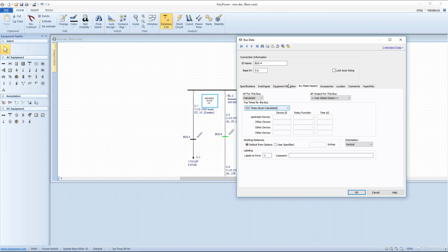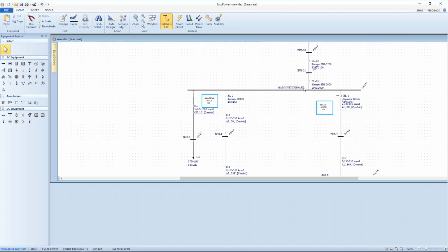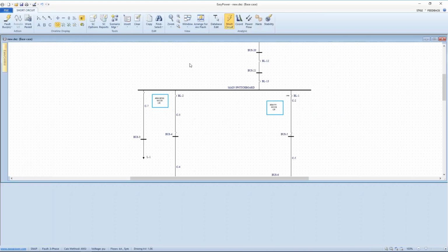we're saying we're going to auto-calculate here. We have a problem in that it will be susceptible to fault current from the main switchboard and also fault current from the battery side of things. If we go into short circuit focus, let's go ahead and look at current. We fault this bus. Again, it'll see 45,000 amps coming from the utility, 470 amps of battery contribution, and